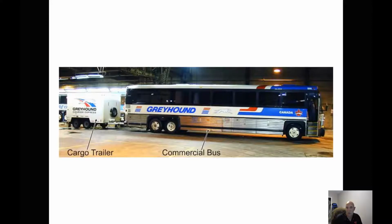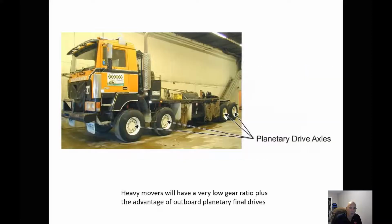When we get into commercial buses, for instance, a lot of the commercial buses are automatics, but at one time they were a manual transmission where you had a mechanical linkage from the front to the back to the transmission that would allow it to shift. And again, we have heavy movers, and they may even have outboard planetaries, and this is going to give them an extra gear reduction in the outboard planetary.